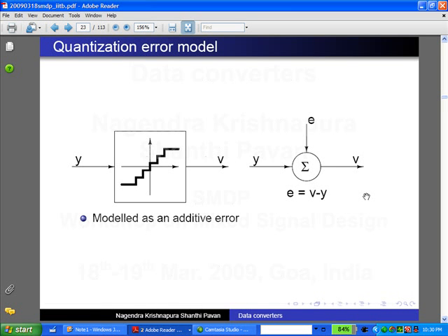When you have some aperture time, there will be some filtering effect. But it's not a significant thing, at least at this level. The effect of aperture time, we have not even come anywhere close to that. And if the aperture time is very small, it is good enough to simply say that the spectrum repeats. Any other questions?